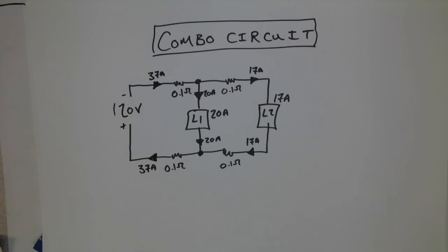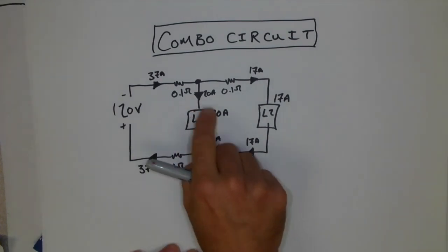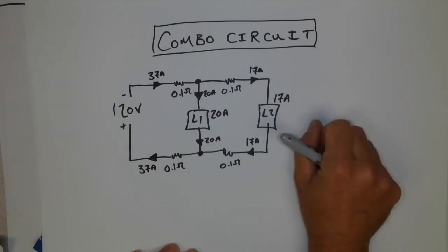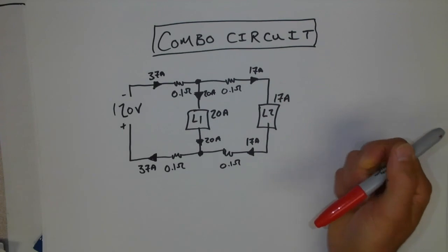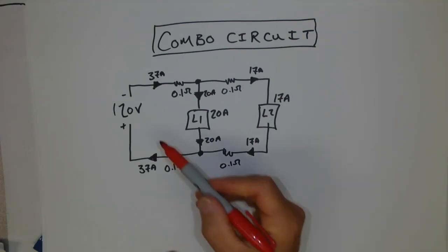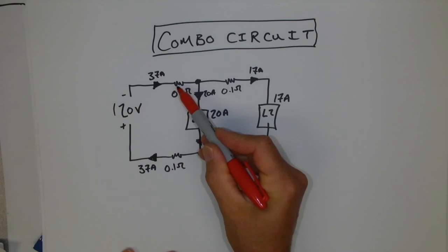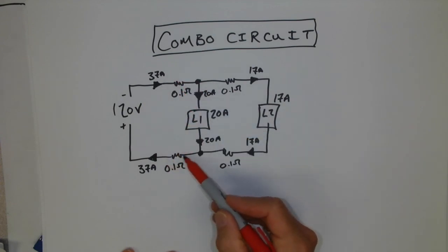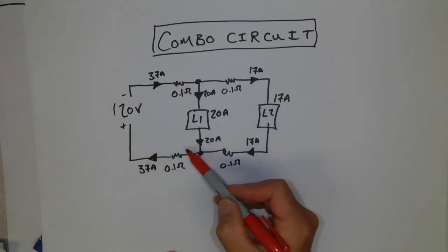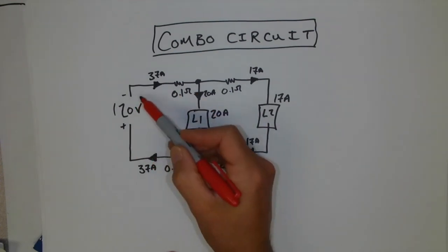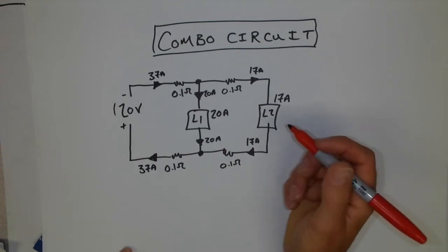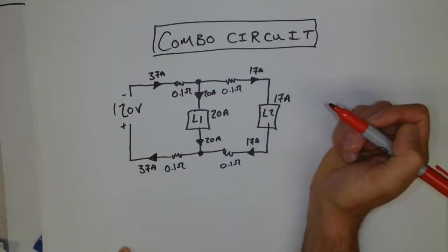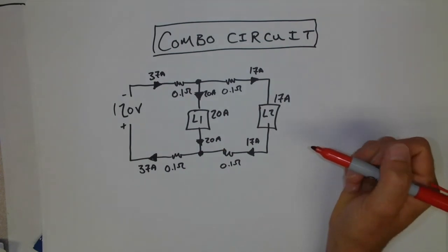Next step, I want to work out the voltages, because with the voltages, I can then work out the power values for absolutely everything. So let's work out the voltage for each of the loads. I'm going to use red for this. Load 1, 20 amps. Well, I need to know what the voltage is on each one of my conductors so that I can treat this like a closed loop and solve for the voltage of my load 1, 20 amp load. So first step, let's work out the voltage across each one of these individual conductors, which is pretty simple